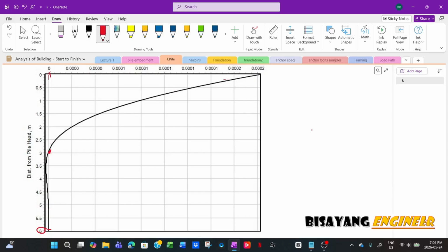But somewhere along this line, between 5.5 probably or around 6, it goes back to the positive side. That means there's a second point of inflection. And if this pile is subjected to lateral load, the tendency, because it's not rotating at the bottom, is that it will go back to its original position.